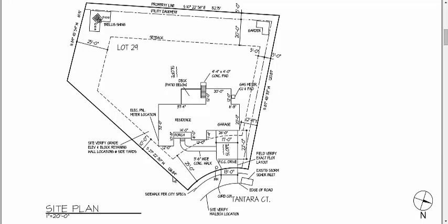So we'll start with that one first. It's 126.84 feet from this lot pin here to this lot pin up there. And this one would be 61.91 feet from here to here, as you can read there. And these other letters and numbers, that gives you direction. So if I'm standing here, if I understand surveying, which you guys will shortly, you have a class in that, it would tell you which direction to start measuring. So using this information here, plus the dimension here, it would tell you how to locate that pin. And then you kind of work yourself all the way around.